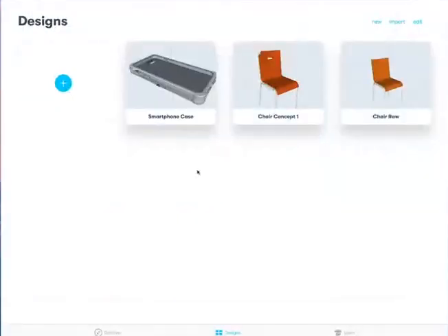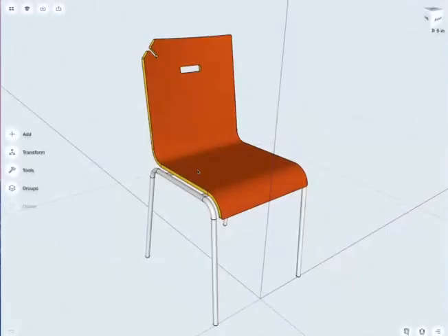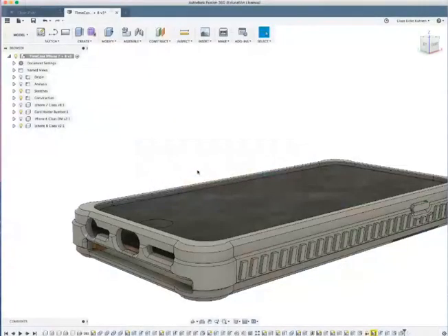So to showcase direct modeling a little bit more, I have, for example, here a very basic shape, and now I would like to quickly do variations to it. So I would like to explore the designs. That is an area where direct modeling very much defeats parametric modeling, because I do not have to be locked to sketches. I can copy and paste and move objects around, which in a parametric application, since we work on the feature tree of one object, we can't really do.